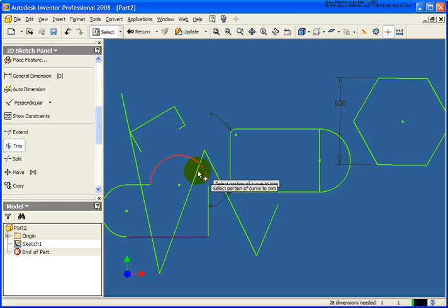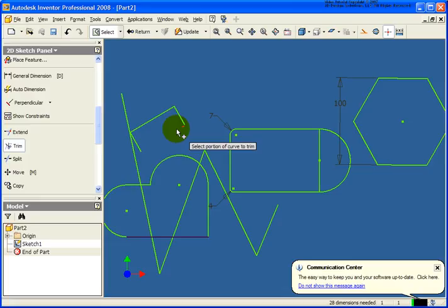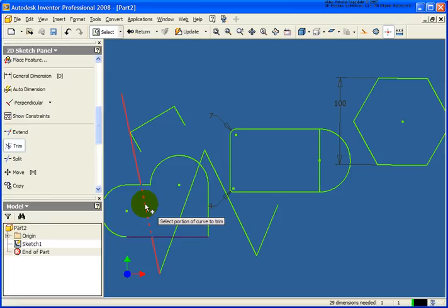But you notice what Inventor is doing, it's taking a look at all the different line segments, and where another line would intersect that, it's going to cut itself short. So in this case, if I selected that other line segment that was left, you can actually erase a given line. So let's continue our adventure down here. I'm going to select inside that shape to trim that back out. And you can see it goes pretty quickly here, but the more line segments you have, the more trimming it's going to be required to do.